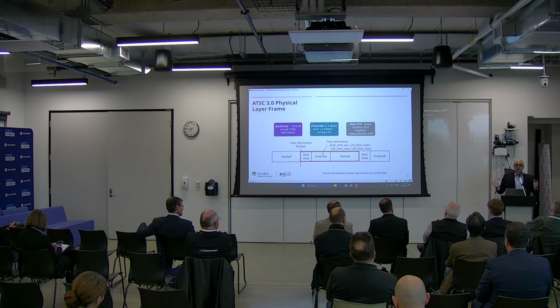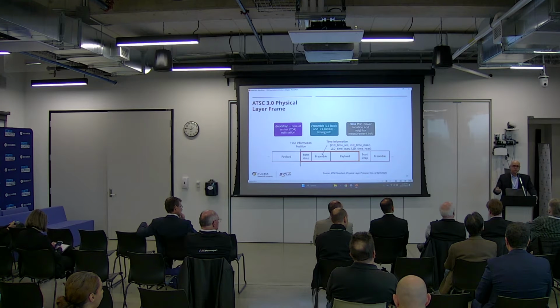It's a payload, and you could choose the modulation, the constellation, all the way to 1024 QAM, and on the other end, QPSK. You could choose different rates of error correction. The lowest is 2/15. So if you choose QPSK constellation and 2/15 error correction, you get a really robust channel, especially if it's coming from a 1 million watt tower just a mile away, a few miles away.